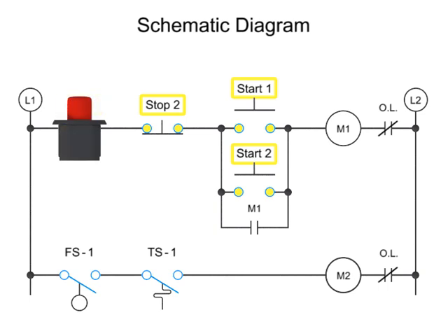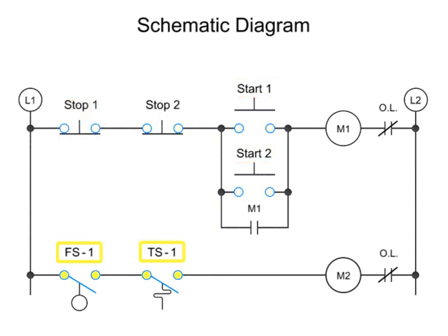Manually controlled components require physical manipulation to work. Automated components turn on and off without manual intervention. A typical example is a float switch found in a sump pump. When rising water reaches a certain level, a float switch is activated that turns on a pump to expel the water from a tank.